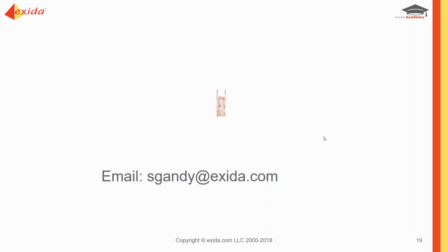Are CFSE individuals considered fit for facilitating a HAZOP workshop? It depends upon their background and experience. CFSE means that you've achieved a certain level of expertise and knowledge in regards to the standards and functional safety. But if you haven't been facilitating HAZOPs, then that doesn't make you qualified to do that. You would need to have experience of doing that, and my advice is to sit in on some HAZOPs initially and then to jointly facilitate to get the experience.